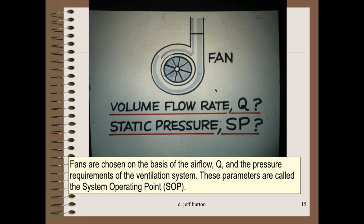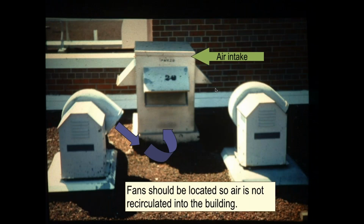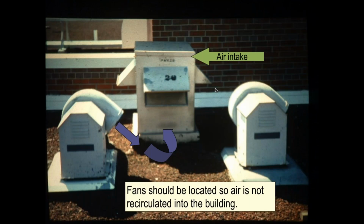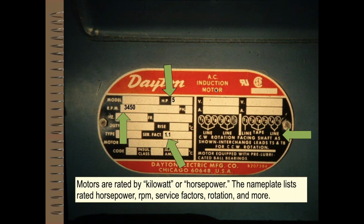So our real interest here is how much air we are going to move and what kind of static pressure it is going to generate so that our hood's going to work right. You want clean out ports on these things. They tend to get dirty. They need maintenance. They're moving parts. You want to locate them in the right spot so they're not near fresh air intakes or openable windows. If there are regulations about the discharge, make sure the heights of the stacks that you design are big enough. They're outdoors, a lot of them, so they're going to deteriorate over time. You've got to maintain them.